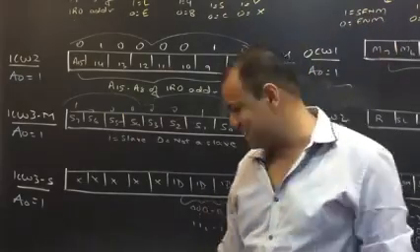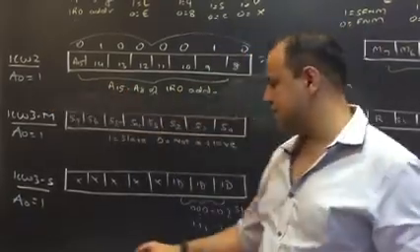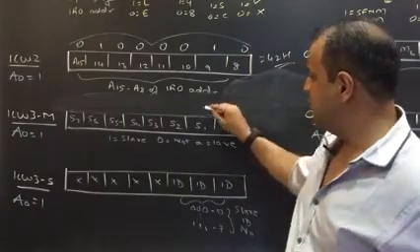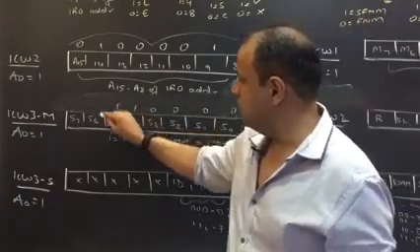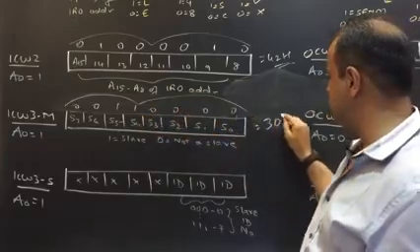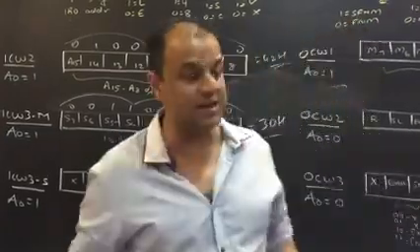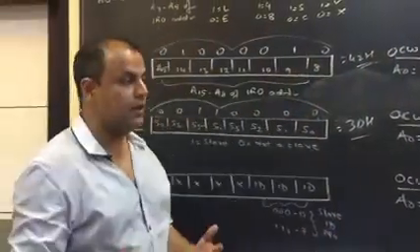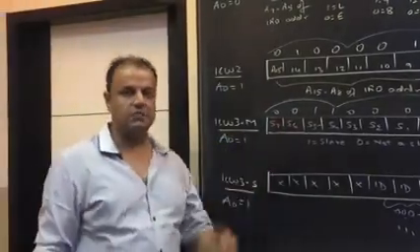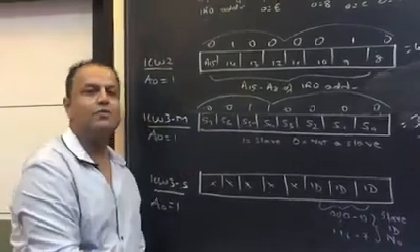Did you understand this? I'll give you another example. Suppose there are slaves connected on IR4 and IR5. That's it. 0, 0, 0, 0, 1, 1, 0, 0. So the number becomes 3 and 0, and your command value becomes 30H. Did you understand? So whatever they say as per the question, if they involve this part, they will tell you which lines have a slave. Whichever lines have a slave, keep them as 1. Which don't have a slave, keep them as 0. That is the ICW3 you give to the master.